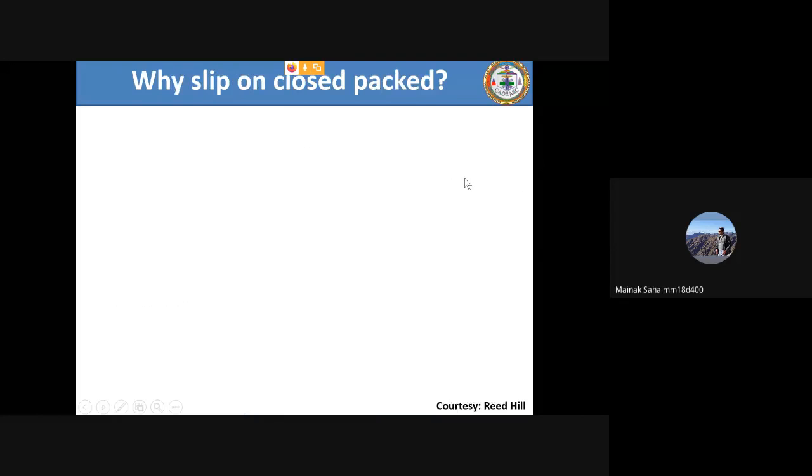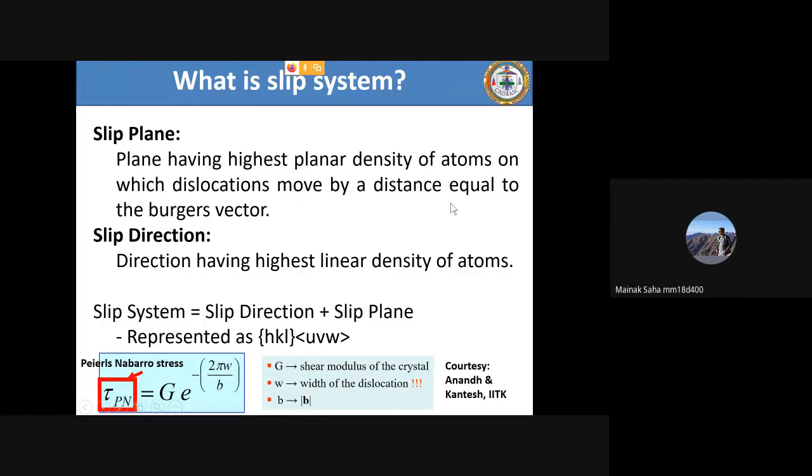So you have a plane of atoms here, and you have a plane of atoms here. Now the distance between the two planes is equal to A. So W is equal to A by 1 minus mu, where A is the distance between planes. And suppose you have the atomic planes here, the spacing between the atoms in a particular plane is equal to B. Okay, so that is the definition. I think now you got it right? Yes, sir. Okay, good.